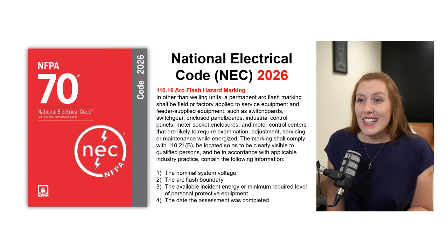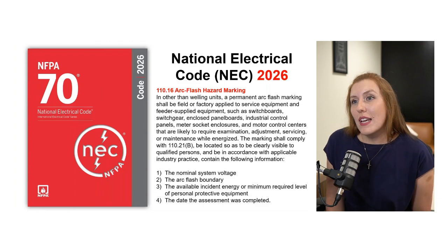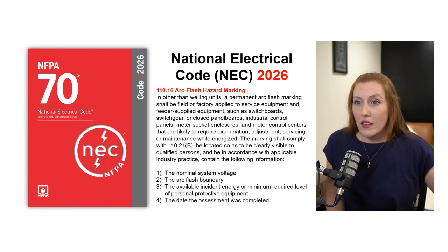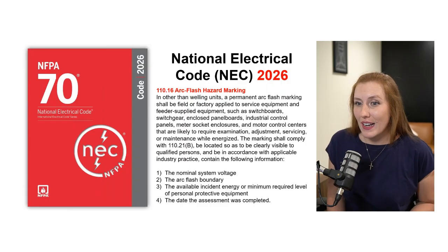Well, the NEC committee, the National Electrical Code, the 2026 edition said, enough of that. We are going to get specific with this. So in 110.16, it has been overhauled. The arc flash hazard marking is not just some generic label indicated, but it's actually going to follow industry best practices, or applicable standards, I should say, such as the NFPA 70E.